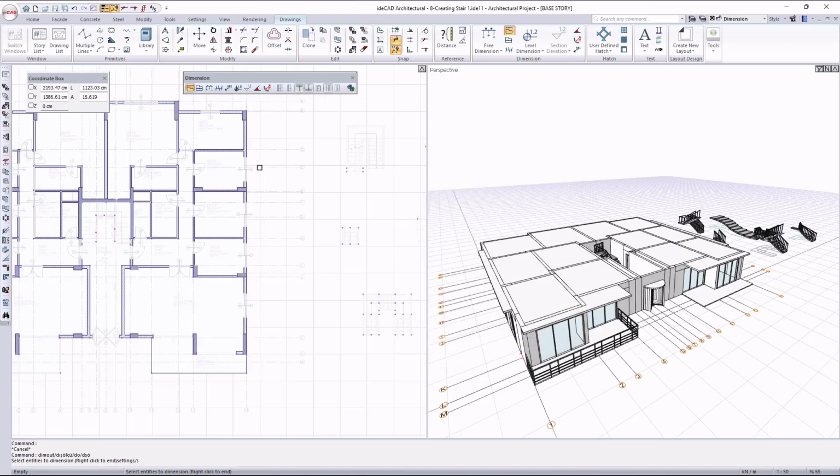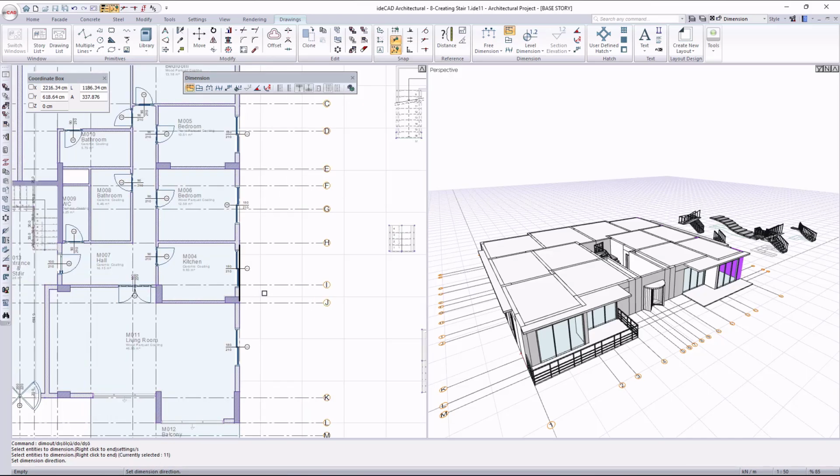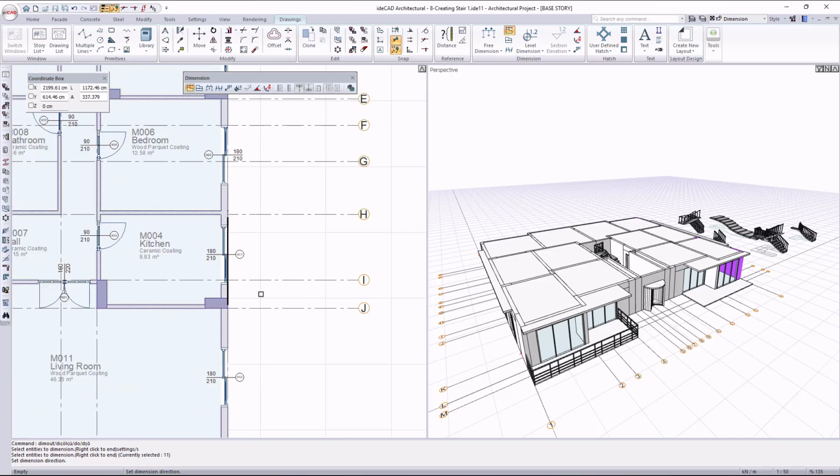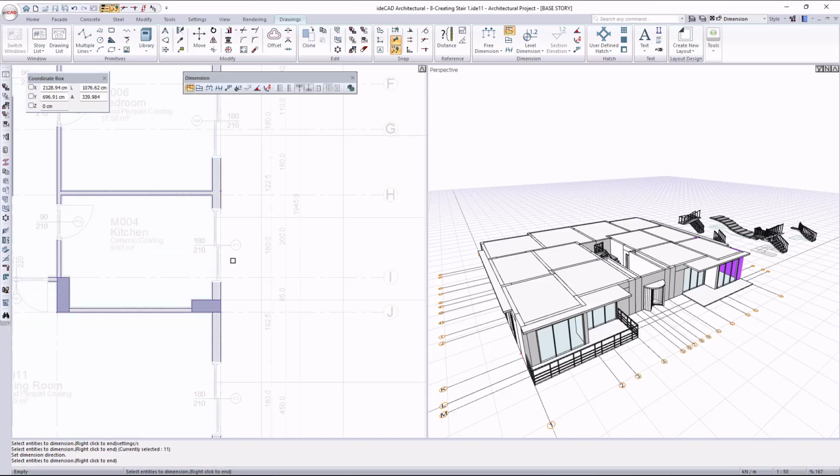The objects to be considered along the facade where the outer dimensioning will be applied should be selected. Once the selection is complete, a right-click is used to finalize it. Then, the wall that will serve as the reference for the dimension placement is specified. While defining the reference wall, a thick reference line is displayed in the selected direction. When this line is clicked, the outer dimension is automatically generated by the program.